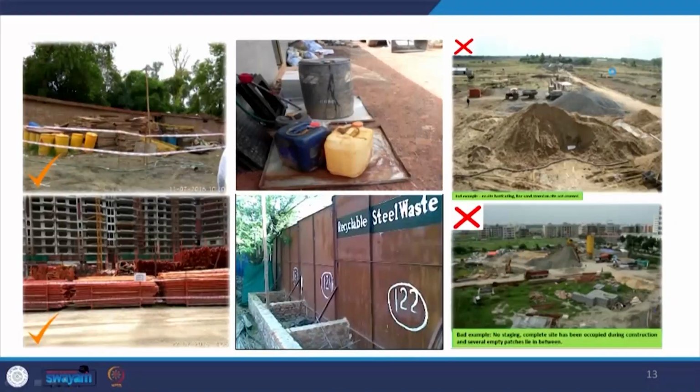For example, there may be chemicals, adhesives, additives which might be used on the construction site. Spilling of those may actually change the characteristic of the site, the soil, forever. It may not have the same characteristics. So we have to ensure that no spilling happens, and that will come with proper barricading and delineating of areas where such materials will be stored, and proper handling of these materials.